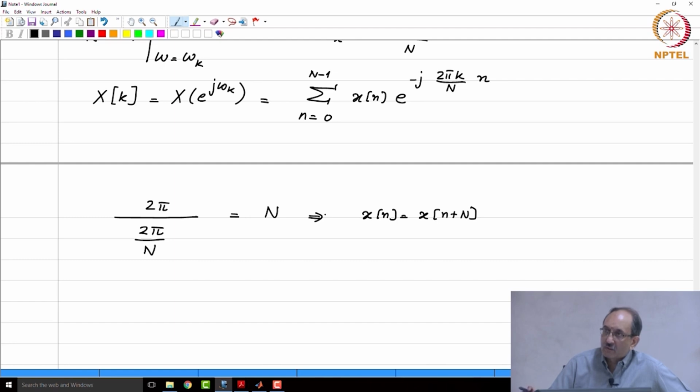Okay, actually I was going to come to exactly that question here. So, you raised it at the right time. When you sample at twice the set of points, you are sampling at a finer spacing. If you sample at a finer spacing, remember in the time domain, if you oversample, the repetitions will occur later, and hence if you sample at say twice the number of points, here also the repetition will occur later, the periodicity will exactly be the number of points at which you sample.